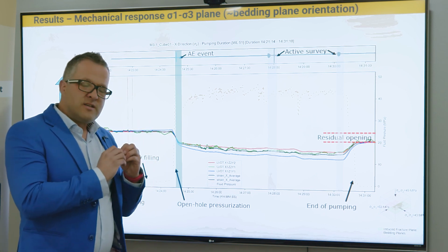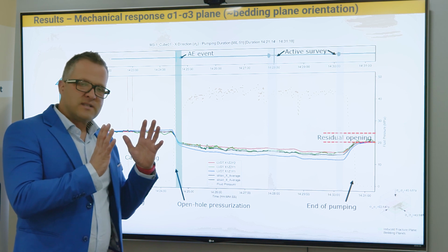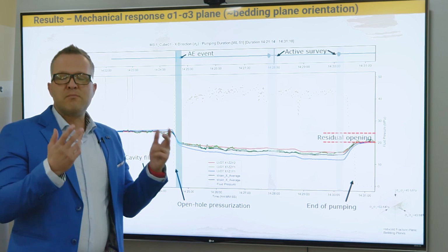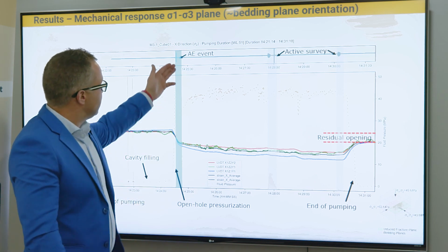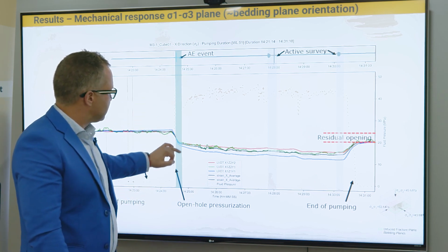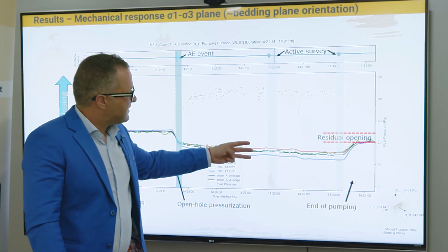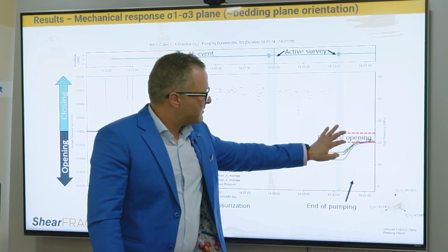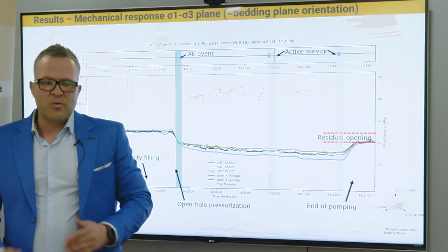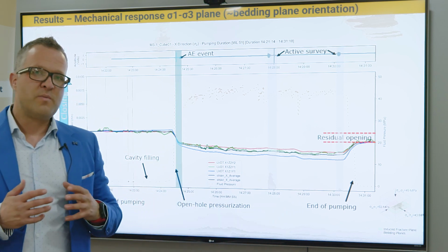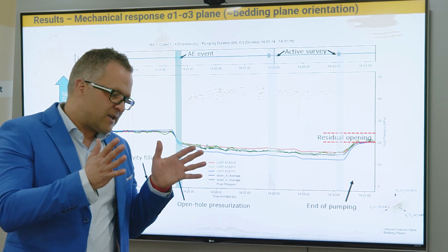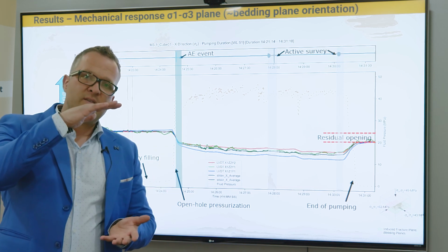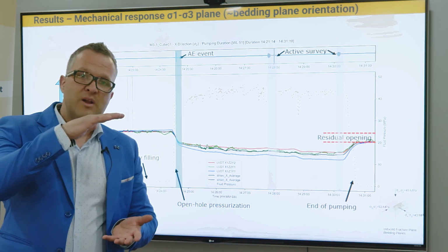So we know the energy going in. We have the acoustic emission sensors coming out. We want to hear for seismic, microseismic events. We did see an acoustic emission event here when it initially broke, and then you can see the different axes here. So ultimately, what we're showing here is there is a residual opening, and we can measure which direction the residual opening is going, if it's in the direction of least principal stress, or if it's in the direction of vertical bedding plane parting.